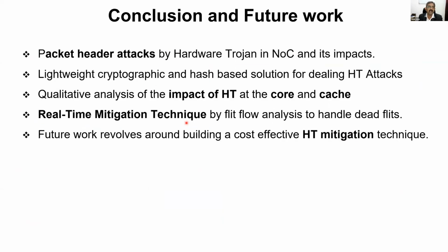So the conclusion: we studied packet header attacks by hardware Trojans in NoC and their impacts. We have modeled it. Lightweight cryptographic and hash-based solutions will be helpful in dealing with these attacks. The qualitative analysis of the impact of HT at the core and cache level is being studied, and we have proposed a few real-time mitigation techniques by flit flow analysis and encryption methods. The future work revolves around building a cost-effective HT mitigation technique.